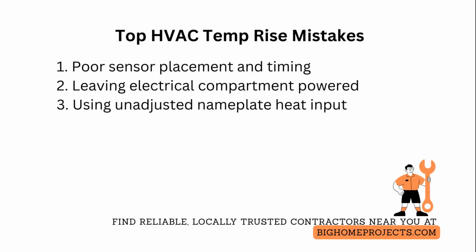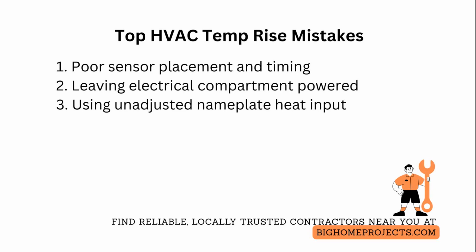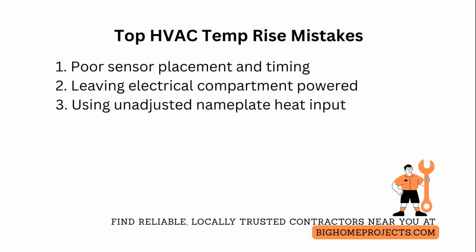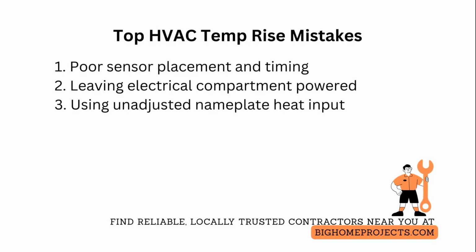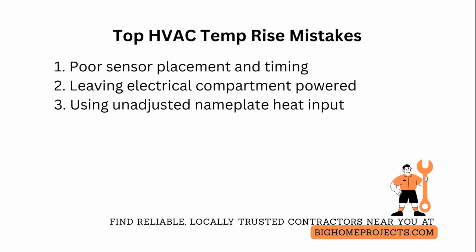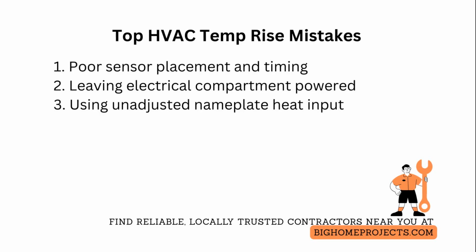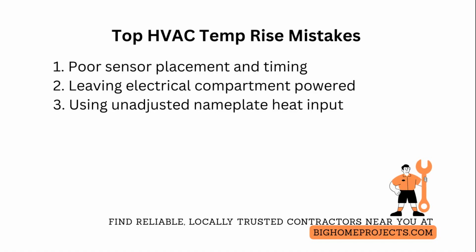One of the other frequent issues is leaving the electrical compartment open while powering the system, creating exposed high voltage shock and arc flash hazards. Fix this by locking out and tagging out power. Verify zero energy with a properly rated meter, and only open compartments with power removed. If a powered test is absolutely required, use insulated remote sensing and a qualified electrician with appropriate personal protective equipment and a documented risk assessment.